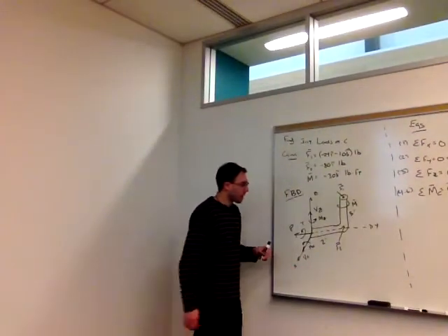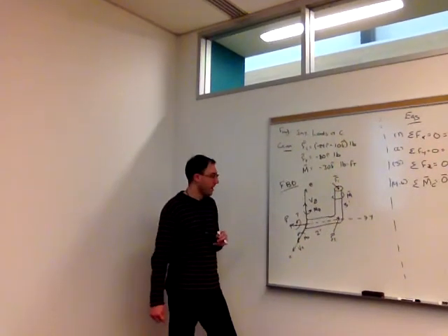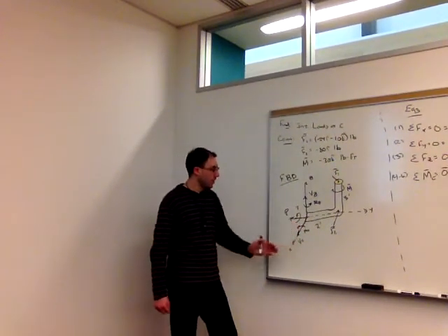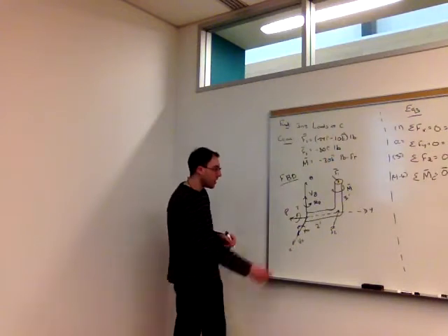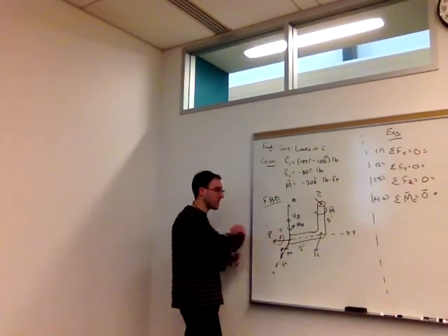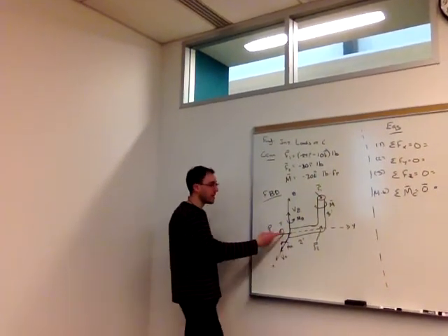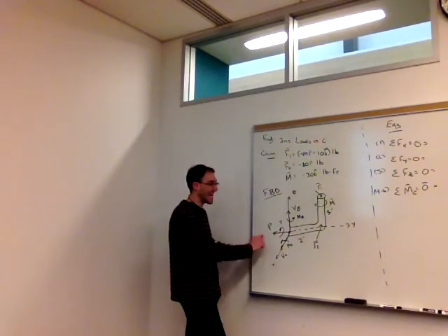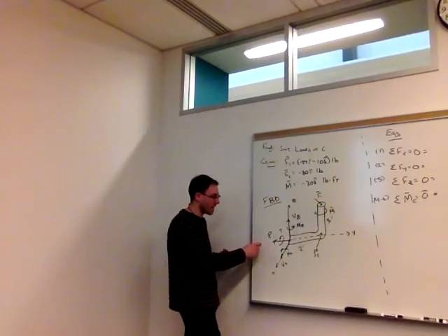So looking at the free body diagram, just to make sure everyone's is correct. Like the last one, we're cutting through parallel to the XZ plane. Our internal normal force has to be orthogonal to that plane. In this case, that means that P points along the negative y direction, like we saw in the last one.